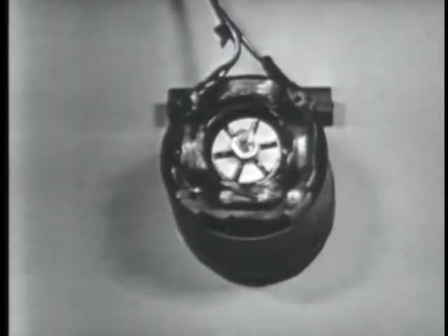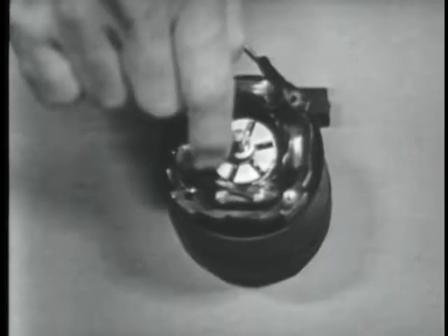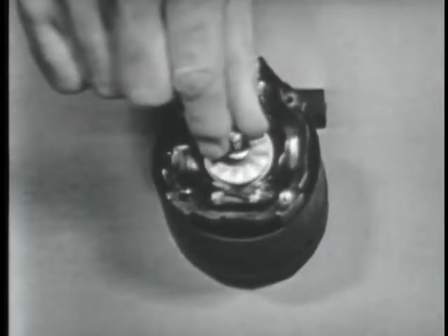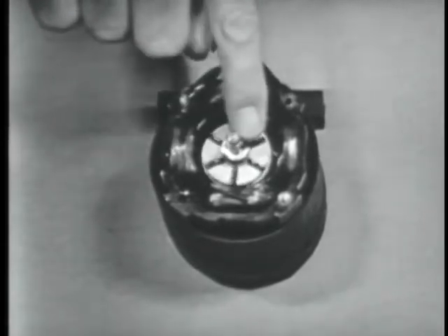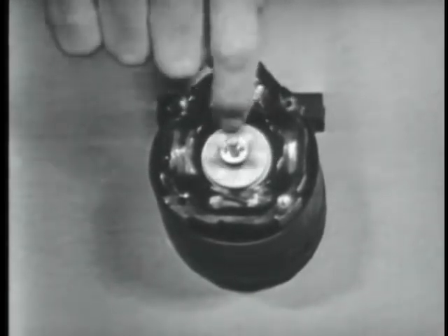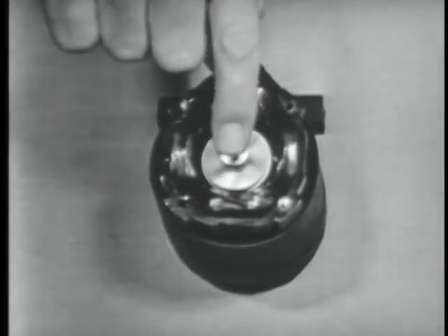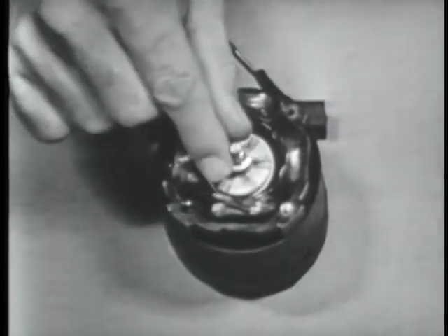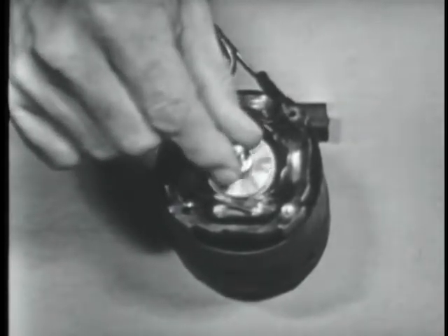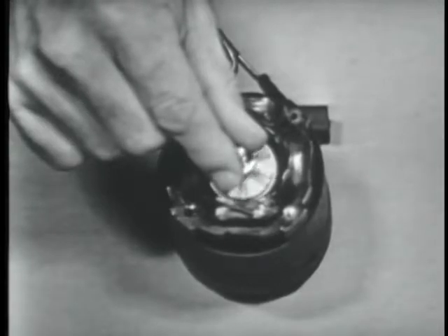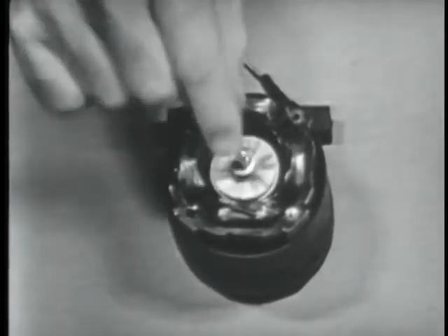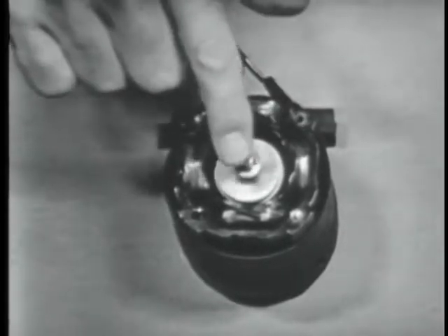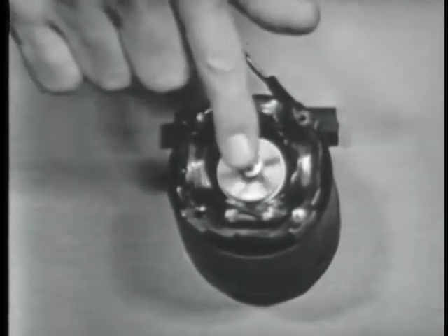Exactly. All right, the rotor of the induction motor does not rotate as fast as the magnetic field because of several forces that act on the rotor. One, the internal load, that is rotor weight, the little fan, the bearing friction, and so on, and the external load on the motor, such as the gears, pulleys, or the fan blade, or in this case, my finger. As I squeeze it a little bit, you can see that it turns slow. Right. Whatever work the motor must do. So the rotor's got to go slower than the rotating magnetic field in order to have relative motion so that it can become an electromagnet.